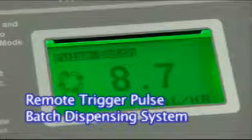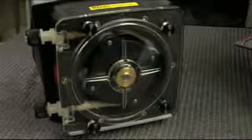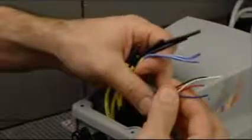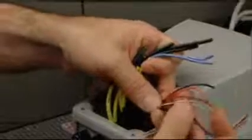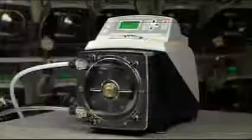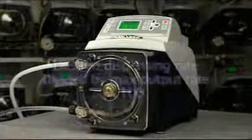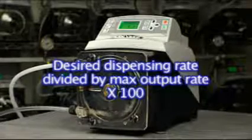Using the A3 pulse input mode of operation, the A3 can be used to dispense chemical as required from a remote contact closure switch. The switch may be a non-powered contact closure type or a powered loop with a maximum power rating of 115 volts AC at 1 amp. Connect a two-conductor signal wire from the remote switch to the red and white lead wires located in the A3 junction box. Input the desired pump output percent of motor speed during batch dispensing.